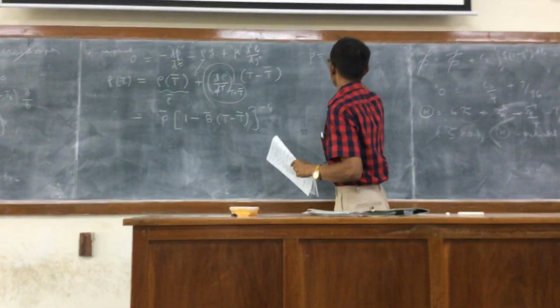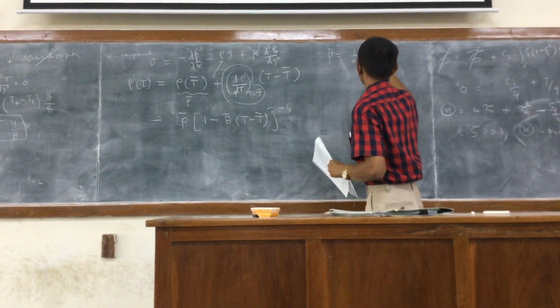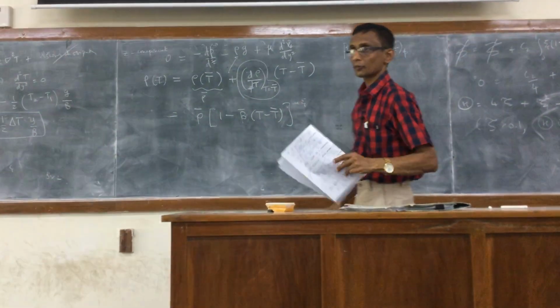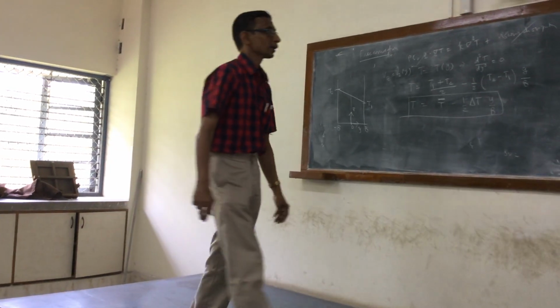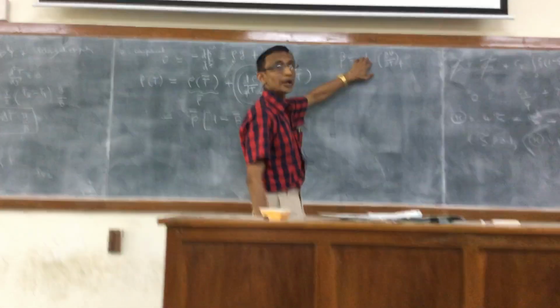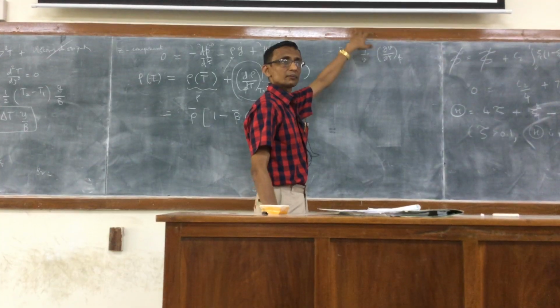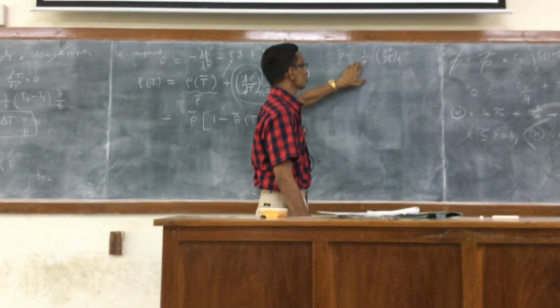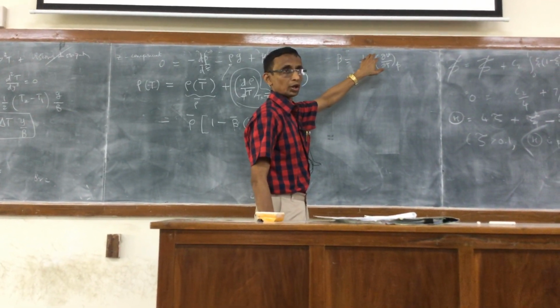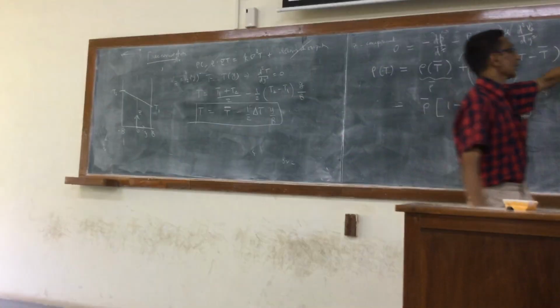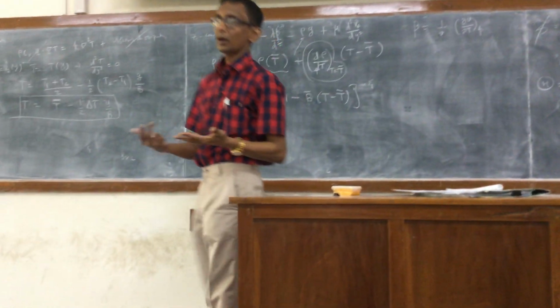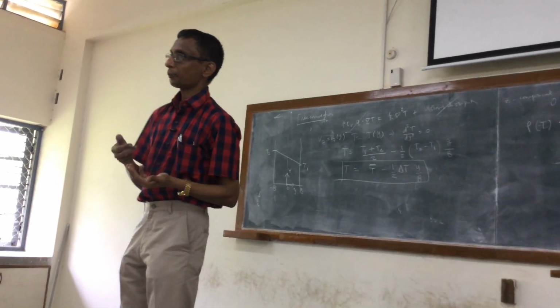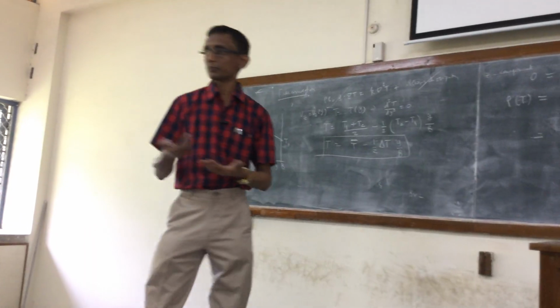Beta, if you recall the thermodynamics, is 1 over V dV by dT at constant pressure, the coefficient of thermal expansion. That is the change in volume or specific volume affected by temperature at constant pressure and per unit volume. So typically, when you're considering fluids in thermodynamics, we choose this as the molar volume, specific volume. But because I have V here and I have V here, I might actually regard V as the specific volume per unit mass, right?